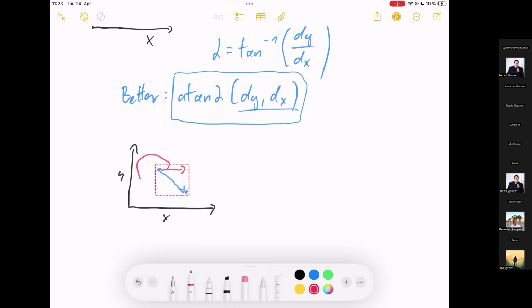And then the robot would rotate by this, like maybe 300 degrees, which is not very smart. So in such cases, please don't always rotate your robot overly long anti-clockwise, but rotate it in the opposite direction, which is much faster. So it's faster and needs less electricity.